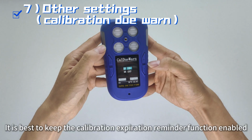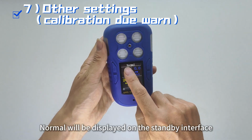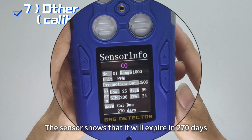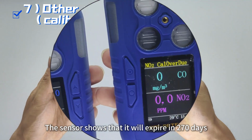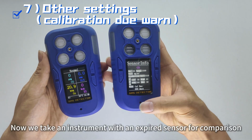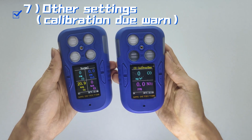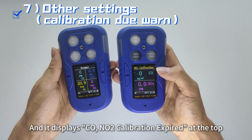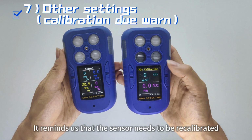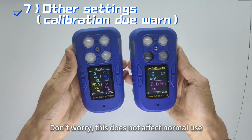It is best to keep the calibration expiration reminder function enabled. Normal will be displayed on the standby interface. The sensor shows that it will expire in 270 days. Now we take an instrument with an expired sensor for comparison. As you can see, the countdown for both sensors is 00. And it displays carbon monoxide, nitrogen dioxide calibration expired at the top. It reminds us that the sensor needs to be recalibrated. Don't worry, this does not affect normal use.